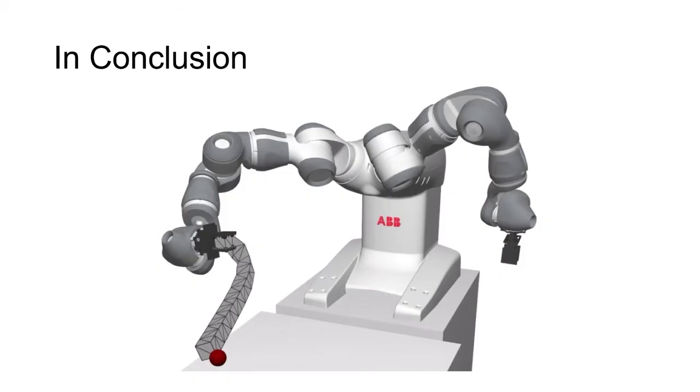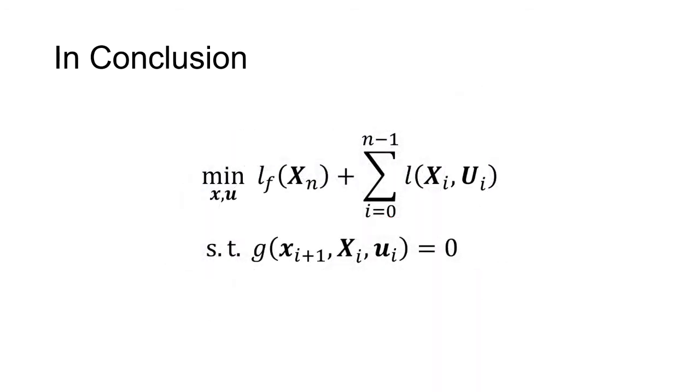To summarize, in this work, we develop, validate, and analyze model-based optimal control techniques for dynamic manipulation of deformable objects. We do so by extending the common trajectory optimization formulation by the use of an implicit integration scheme. We study both the batch-Newton method and the stage-wise DDP approach and compare their performance in the context of our problem setup. Detailed information about this comparison can be found in the paper.